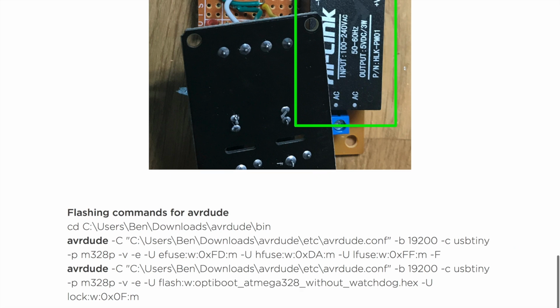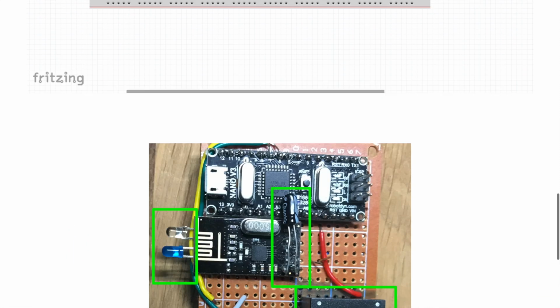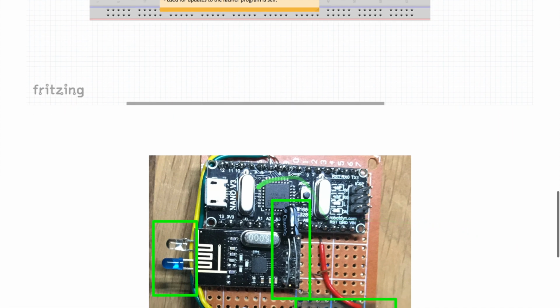Another small thing to be aware of is once you change the bootloader to use the nRF24 library instead of the UART, once your sketch is up and running and it also wants to use the nRF24, you will have to have the same base code for both, the sketch and the bootloader, since both code parts are using the same hardware.